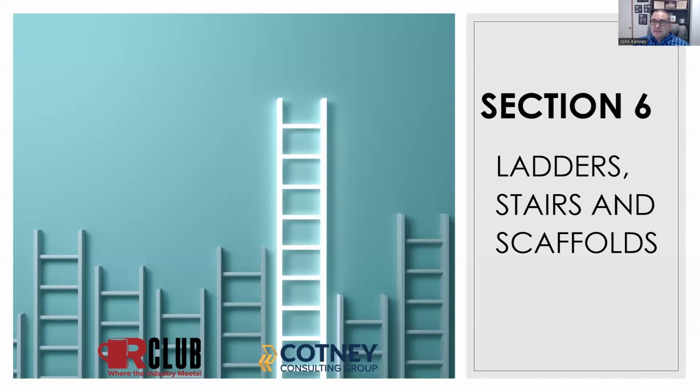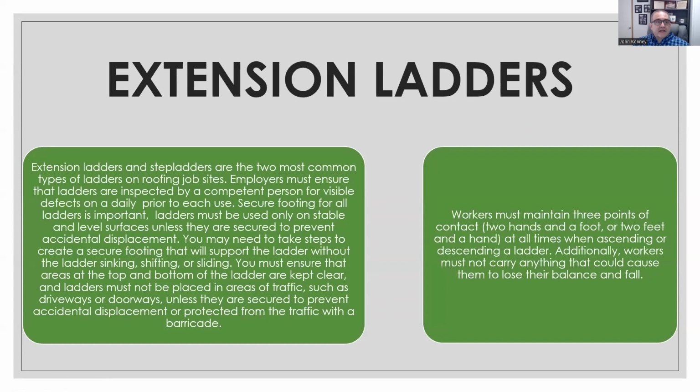Ladders, stairs, and scaffolds. Extension ladders and step ladders are the two most common types of ladders you're going to find on roofing sites. Employers must ensure the ladders are inspected by a competent person for visible defects on a daily basis prior to each use.